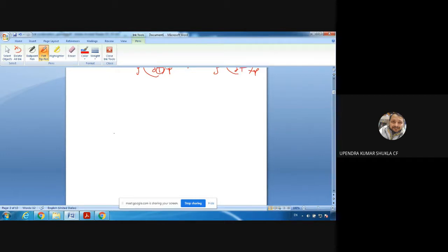Because shear stress, as you're able to recall, how is shear stress defined? Newton's law of viscosity, mu del Vx. Suppose this is Vx is changing. Suppose this is the flat plate. Now fluid is striking this surface. Before striking this surface, the fluid had the uniform velocity. Now, once it strikes the surface, you will find that this surface is stationary.